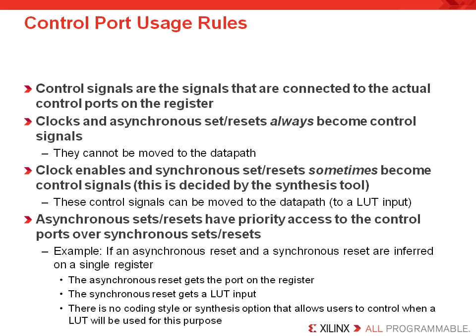It is important for you to remember that synchronous sets and resets, as well as clock enables, can be made for your design by routing to a LUT input, rather than connecting to the corresponding port on the flip-flop. Now, this is part of the basic functionality of the lookup table. If we can drive the clock enable to the LUT input and then take the output and drive it to the clock enable port, or not use the clock enable port at all, then we can actually build some additional functionality. So one of the nice things to keep in mind is the more you use synchronous sets and resets and clock enables, the more likely you have the ability, or given your synthesis tool the ability, to not use the dedicated port on the register for just that control signal. Instead, you could use it for an asynchronous reset or an asynchronous set if you need it.